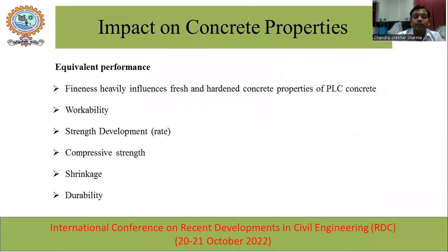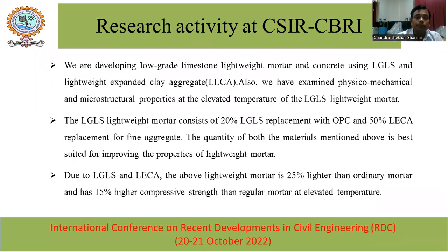Concrete properties, impact on concrete properties of the PLC. Fineness heavily influences the fresh and hardened concrete properties of PLC concrete. Workability also increases without decreasing the compressive strength of PLC concrete. The rate of strength development is improved. Shrinkage of PLC concrete decreases. Durability increases.